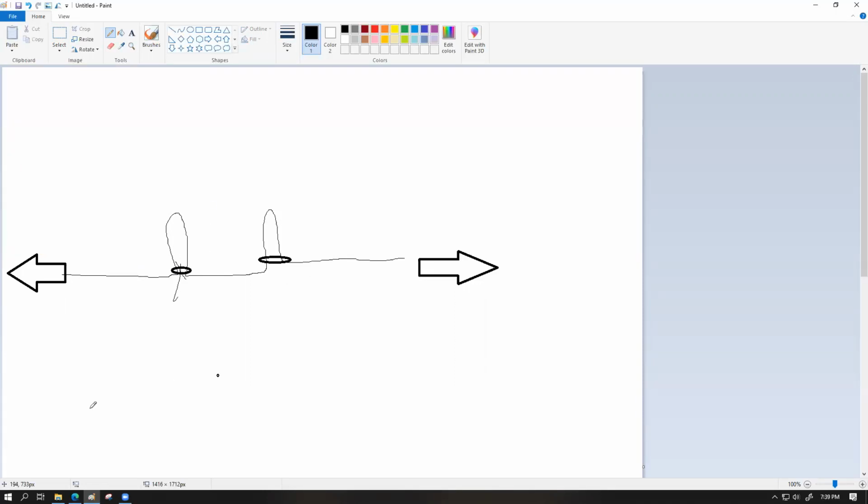And whenever this wire becomes stretched, for example, let's say now this thing doesn't exist, but we still have this one available, and then this will be responsible to withstand that force for a significant portion. Later, this can break down again. So for each individual strong part of a loop of this kind of shape, whenever these bondings break apart, the material is going to give up a little bit, and at those points we're going to have a little bit of variation of forces. Let's say you're pulling onto something by a very strong force, and suddenly that material gives up resisting that force for a small duration, and then it holds up and comes back to it again. So that's the sort of behavior that we are seeing.